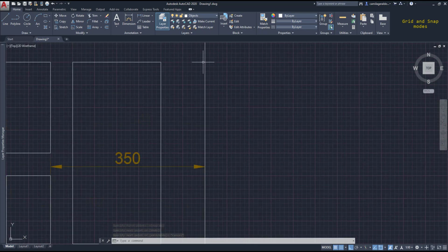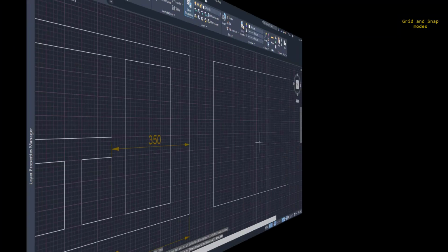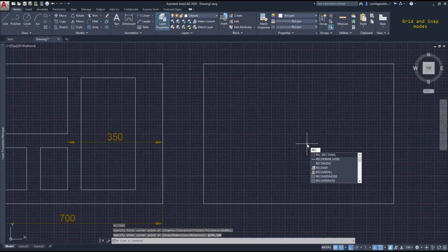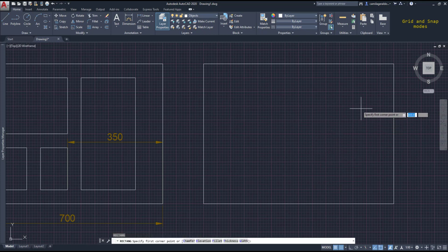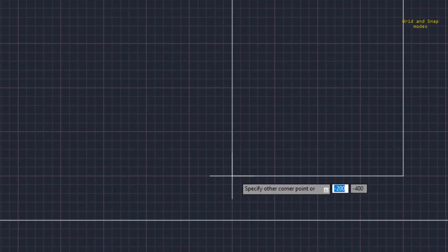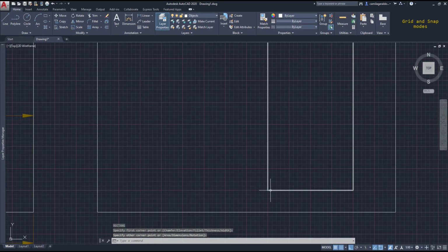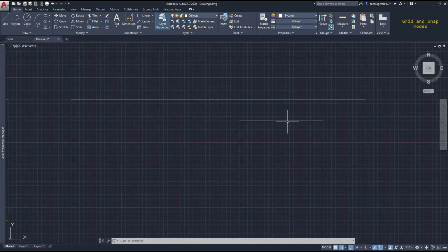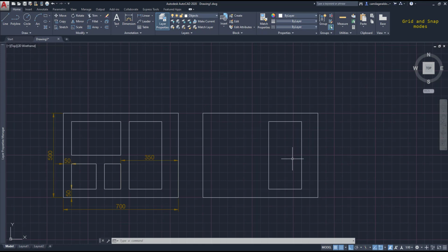Now have a look to this drawing. We can easily guess the distance between some points, if they are not that far away. For example, this distance is 100 millimeters, and the width of the rectangle is 200. Because there are 4 big squares, 5, 10, 15, 20, you can just count them. So to draw that rectangle with the grid is actually easy. This is the first corner, then the opposite will be 4 large squares to the left and 1 above the line at the bottom, so click there. You can zoom a bit to make sure that you click on the correct point, it's better.